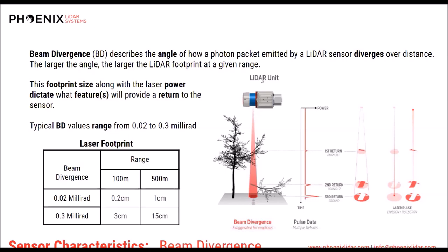Well, pure density doesn't necessarily dictate whether you're going to capture a power line or not on a given scan. The characteristics such as we've been talking about today, making sure your pulse repetition rate and angular step and beam divergence are all in tandem with each other for your given platform speed, so that your laser is never crossing over a thin object, either in the angular step as the sensor moves down its flight path, or in horizontal.